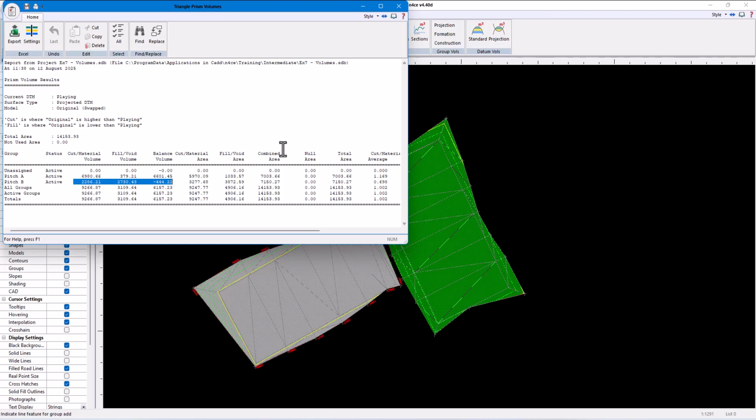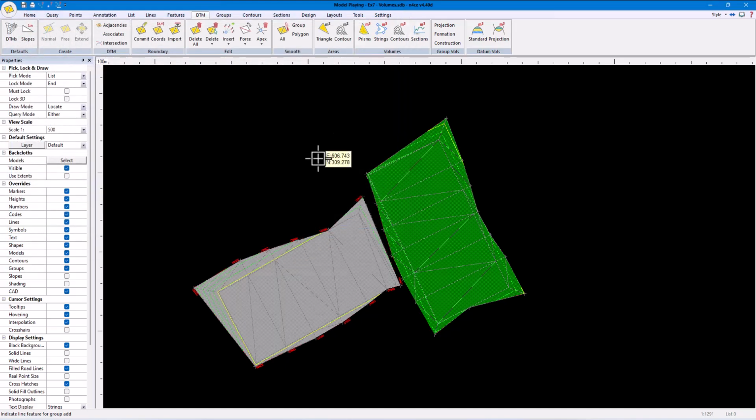The totals beneath then combine these figures. So as it stands, the surface design would currently generate a surplus of 6,157 cubic meters of material to make this design work. Therefore, our task is to rework the levels of the pitches and hence recalculate the batters so that the pitches can be constructed to achieve a net overall balance of 0, or as close as we can get it.